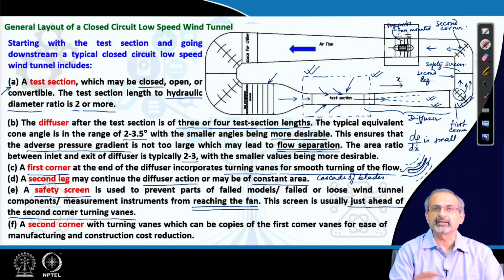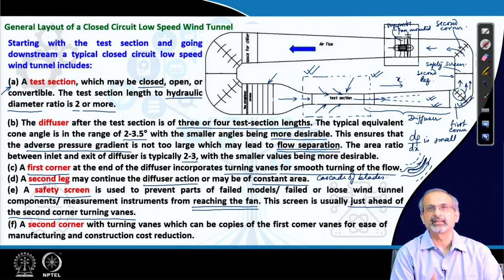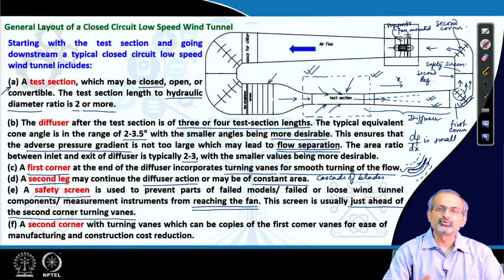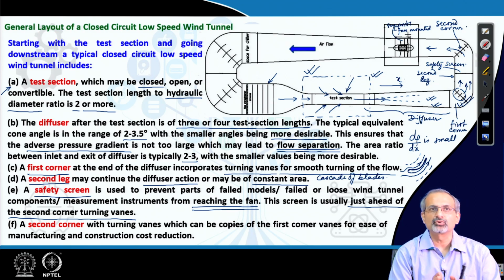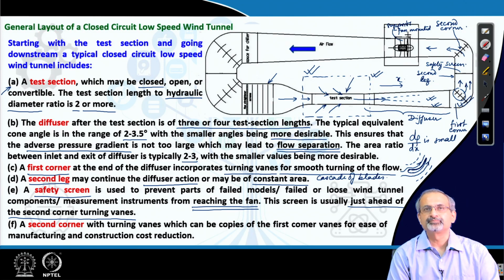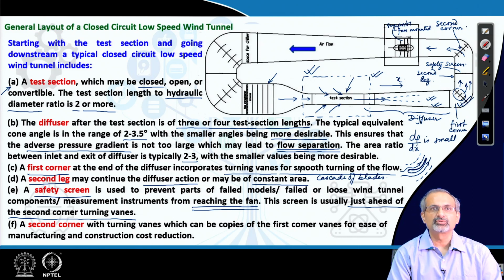So, it gives a nice aerodynamic shape for the flow to move externally past it, and then the motor is kind of shrouded inside that. The cables make their way through those supports to the motor. They are also housed within those fairings, and then downstream of the fan, there are also flow straighteners.